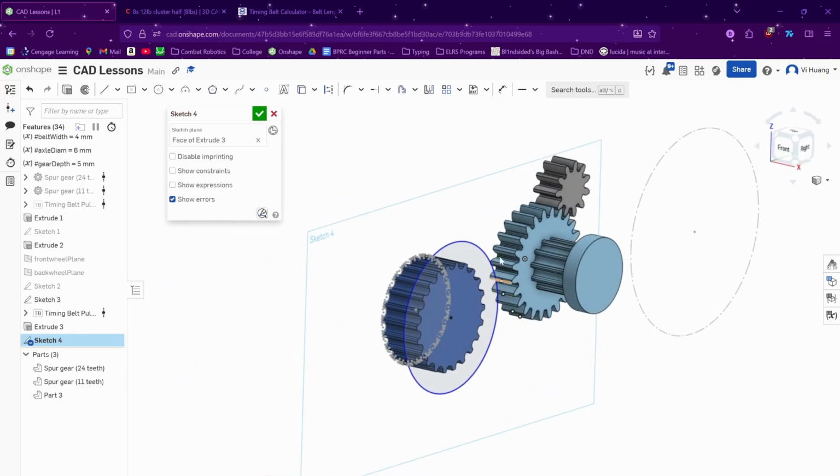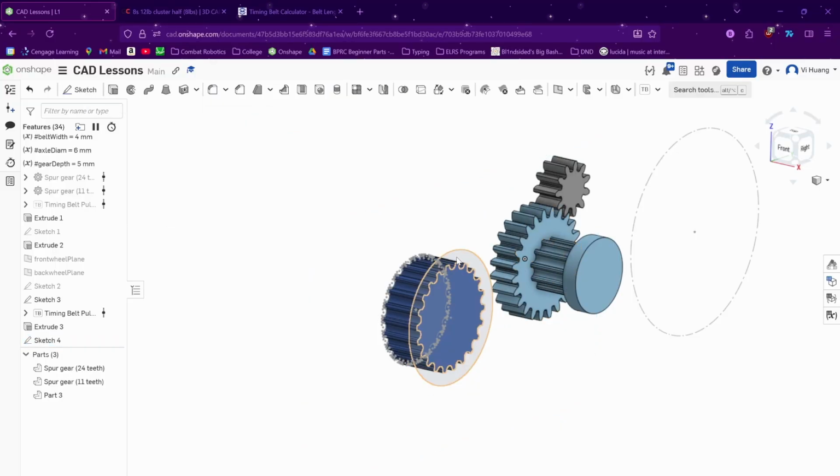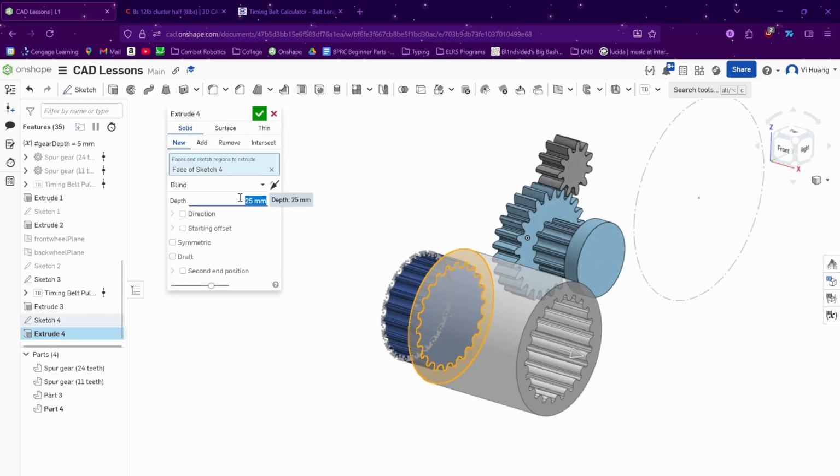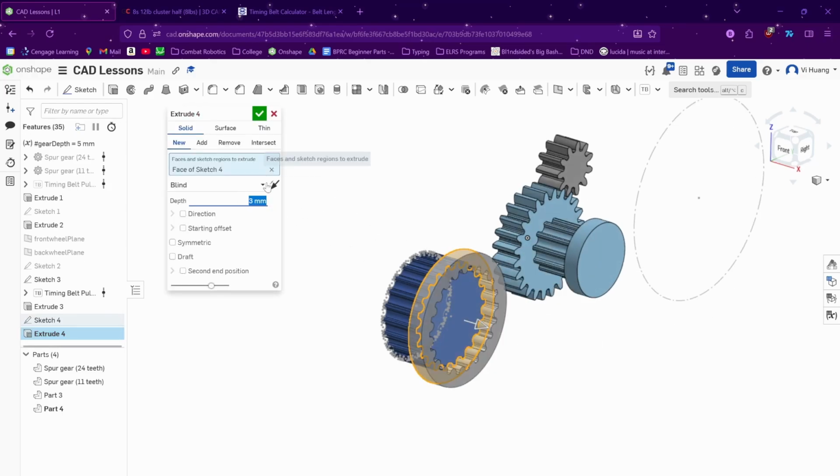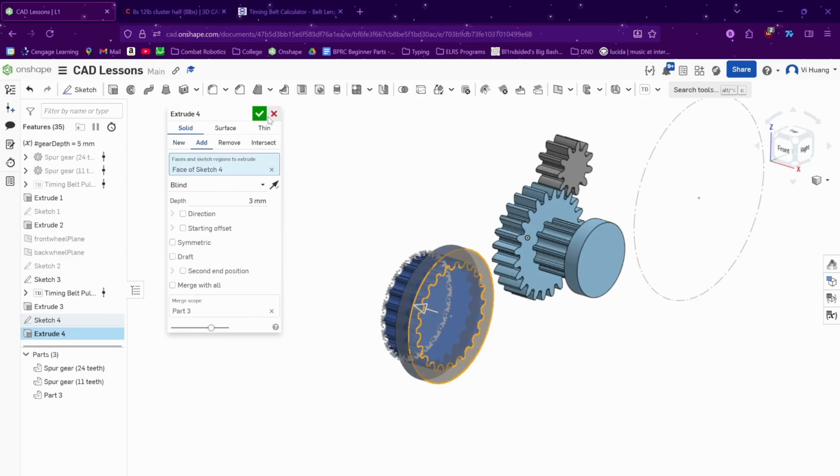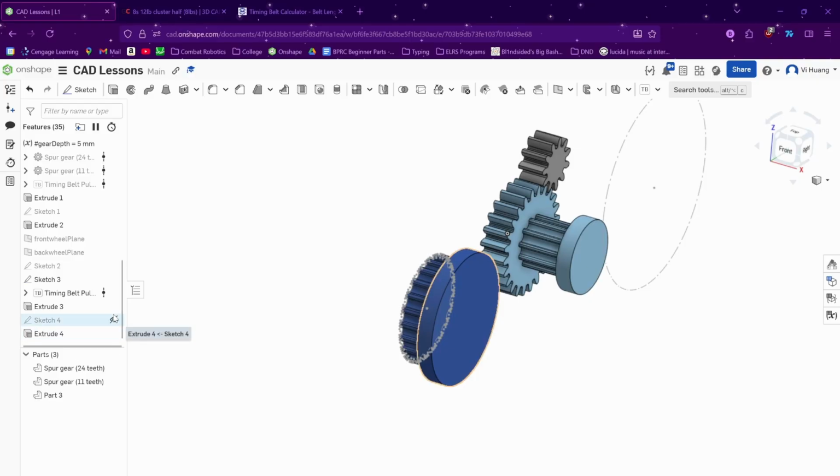That seems like a lot of extra work that I would rather not do. So instead, I will only create one gear in the cap and then extrude this 3 millimeters. Now, in a case where you have two differently sized wheels, you will have to just do this 2 times. There's not really a way to make this any less painful.